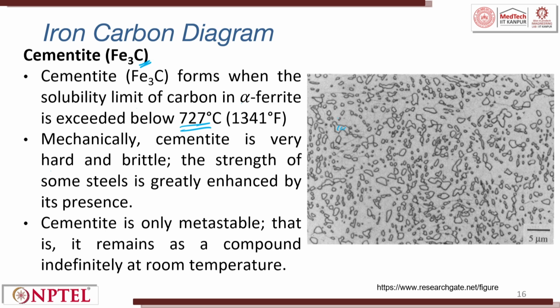So, if there is a soft material and a hard material and there is a crack, the crack gets arrested. And since it is hard, it is also brittle, so you do not have so much ductility. The strength of the steel is greatly enhanced in the presence of carbon. Cementite is also only metastable, that is, it remains as a compound indefinitely at room temperature.